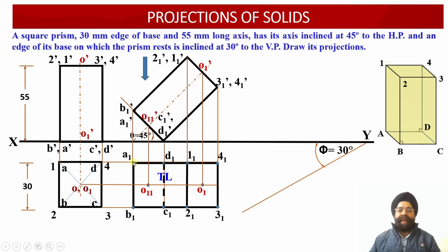So now using the method of rectilinear projections, we have to transfer the plan projection view which we had earlier obtained at an angle of 30 degrees in such a way that points C1 and D1 will be obtained as C2 and D2 onto this orientation line which has been drawn at an angle of 30 degrees. Now we know the size of this rectangle. We know this edge over here is going to lie as C2 D2.